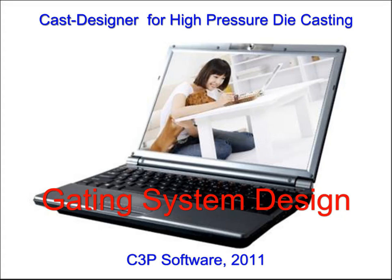Usually, the main process includes, at first, we need to check the geometry feature of the part and the main quality requirement. The second, we will define the parting method and the location of the parting plane, also the location of the inner gate, center of the piston. Then, we can use the design advisor or other expert system and CAST Designer to get the major parameters for the casting system. The last one, also most important, we will use CAST Designer to generate the 3D gating system geometry instead of any CAD system.